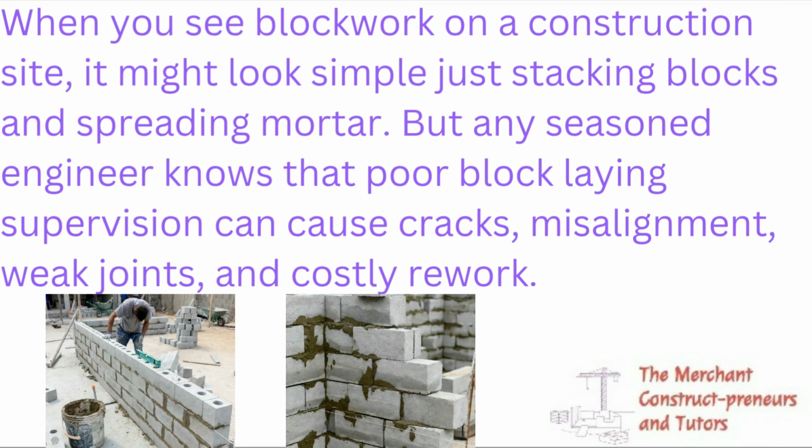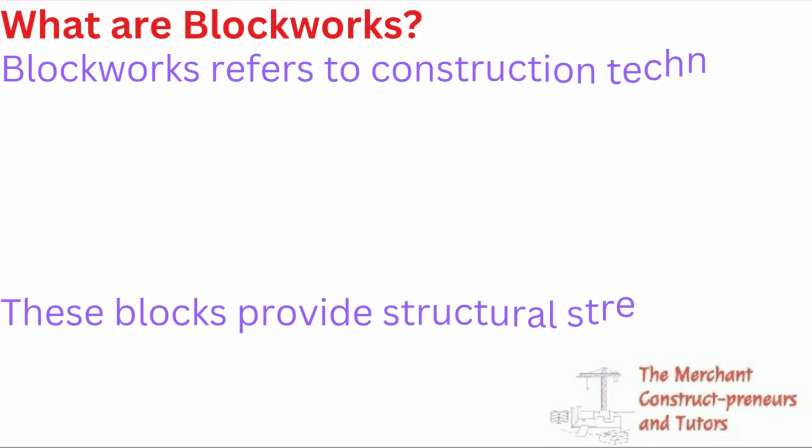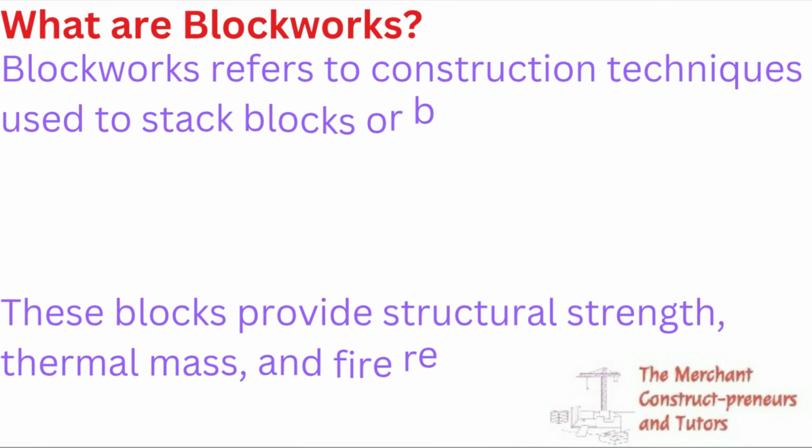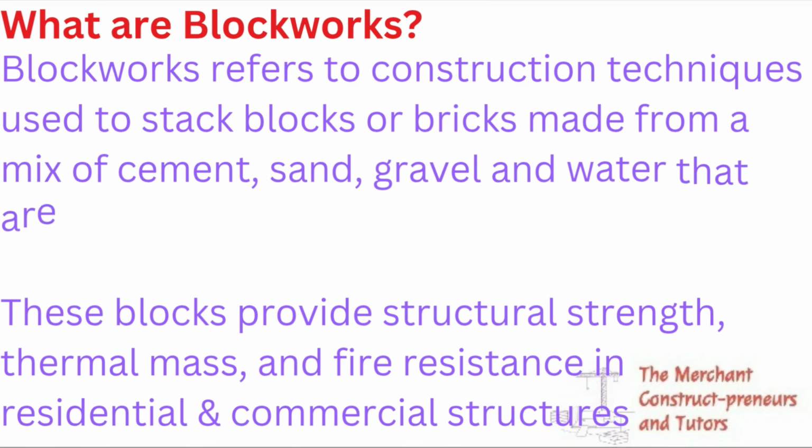So to ensure that this doesn't happen, because once you give the workmen these things to do, they're just interested in their money. They do whatever they want to do and just get out of the site. But as a supervisor, you need to ensure that everything is okay, from the verticality to the alignment to the straightness to how neat the blocks are laid.